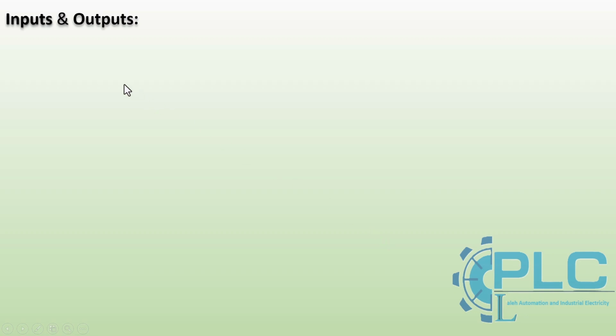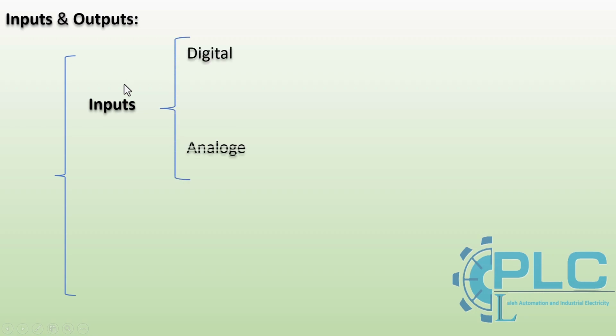PLC inputs can be categorized into two main types: digital inputs and analog inputs, depending on the type of signals they receive from field devices. First, let's look at digital inputs. Digital inputs work in a binary manner, meaning they can only detect two states, on or off. When the input is on, it means the signal is active, and when it's off, the signal is inactive. This simplicity makes digital inputs ideal for on-off operations.